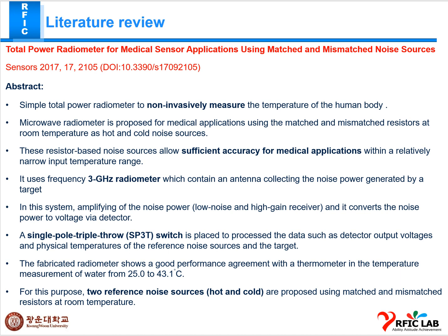Sufficient accuracy for medical application is relatively narrow in input temperature range, and it uses a 3 gigahertz radiometer which contains an antenna collecting the noise power generated, and after amplifying the noise source power, it converts the noise power to voltage via a detector.